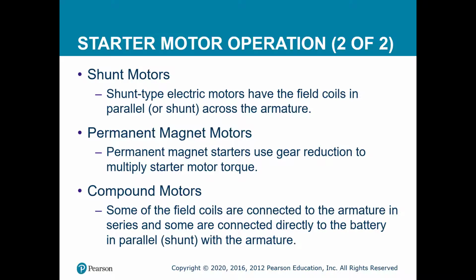Compound motors have some of the field coils connected to the armature in series, and some of them connected directly to the battery in parallel. So that way you get kind of the best of both worlds. You'll see this in some Ford, Chrysler, and GM type starters.